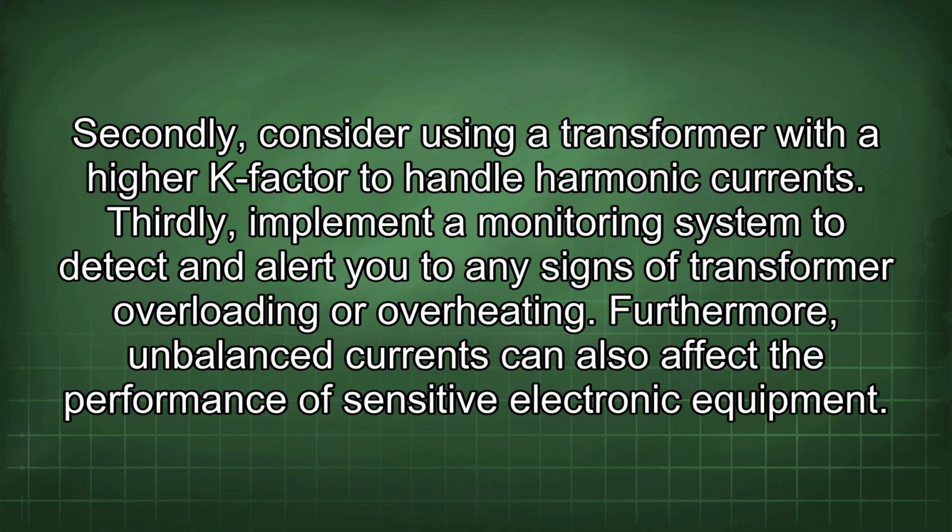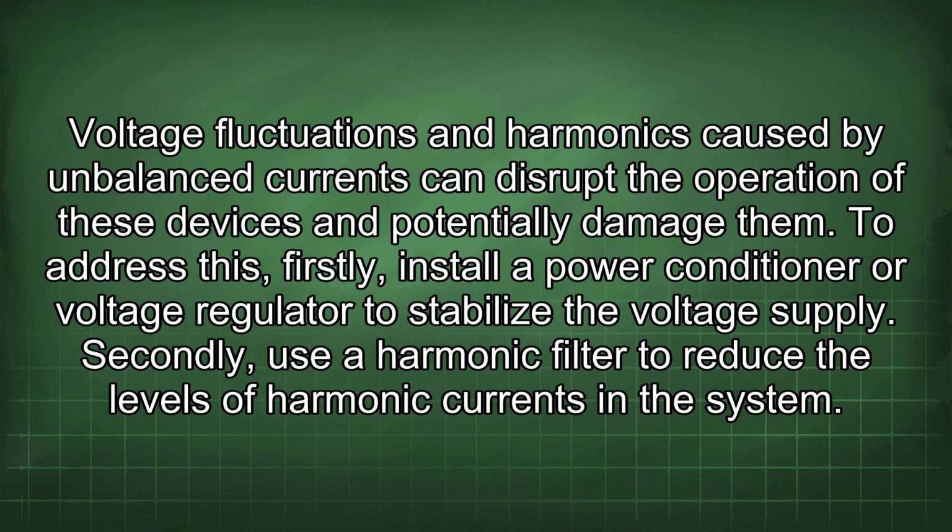Furthermore, unbalanced currents can also affect the performance of sensitive electronic equipment. Voltage fluctuations and harmonics caused by unbalanced currents can disrupt the operation of these devices and potentially damage them. To address this, firstly, install a power conditioner or voltage regulator to stabilize the voltage supply.